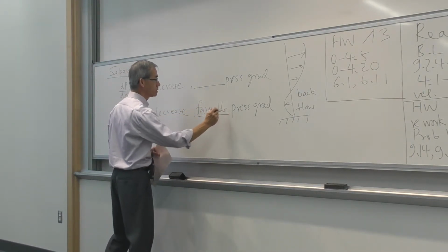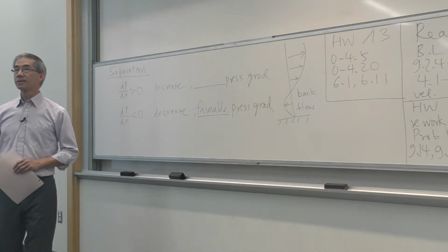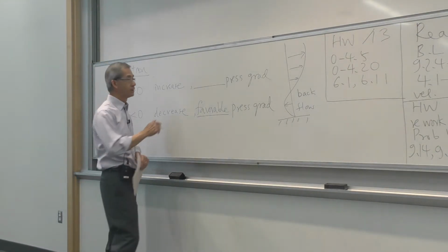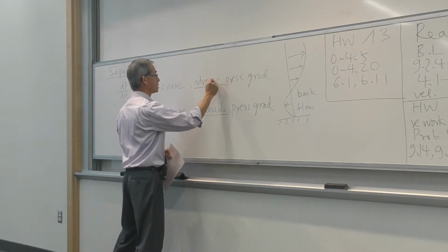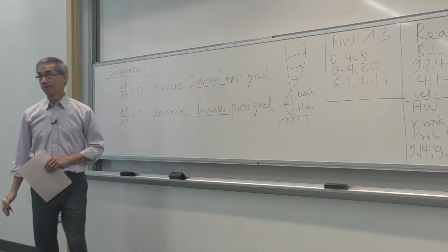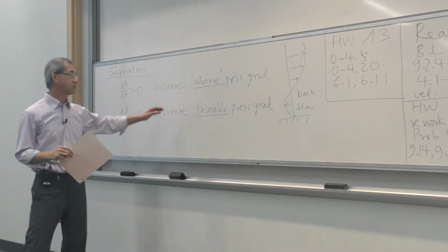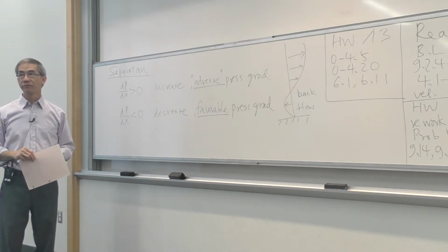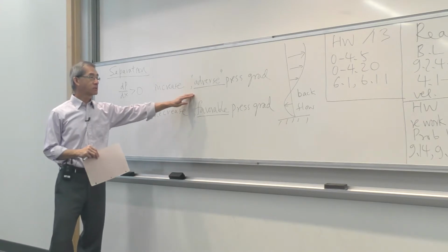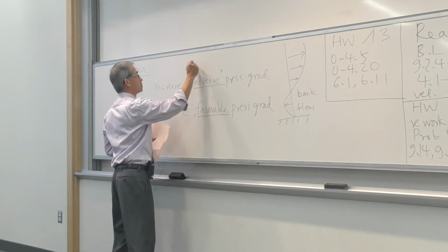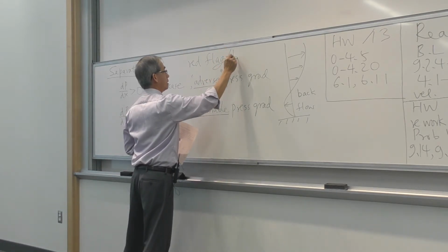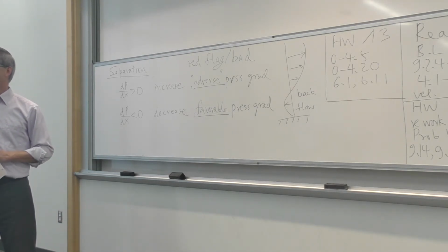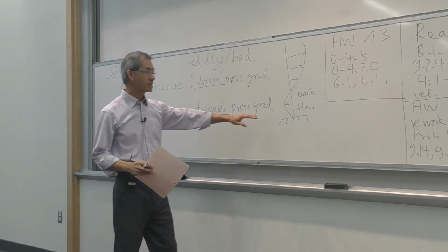And it's very important. It just seems so trivial. It's the next one that I want you to make sure you never forget. What do we call that pressure gradient? Adverse. When you hear the word adverse, does it mean good or bad? Bad. And it is. Anytime you have a device where the pressure is increasing downstream, a compressor, a diffuser, it's called adverse pressure gradient. And this is where I want you to raise the red flag and be on alert, because it will cause the boundary layer to do what? Separate. Separate, for the reason we discussed last time.